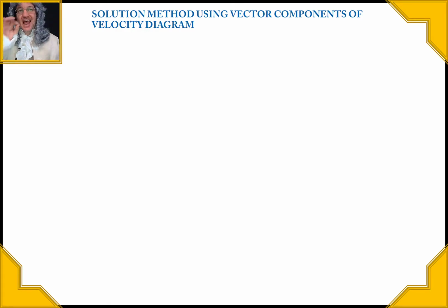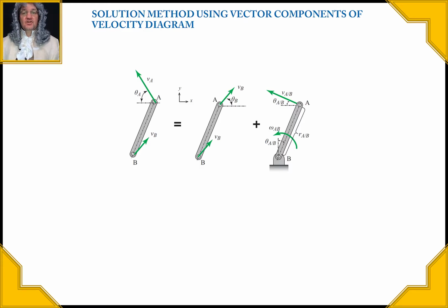So making an accurate drawing with the proportions, maybe using a ruler and scaling things, can be very, very helpful in doing this. Okay, so here is a generic velocity diagram. Instead of using the boomerang, I picked one where the velocities will maybe make it a little bit of a larger triangle when we're done with the thing. All right, so we were writing out, we want to find the velocity of A, and we know the velocity of B, so we have this relative motion of velocity of A with respect to B from there.